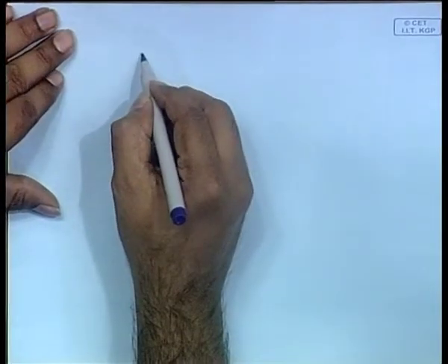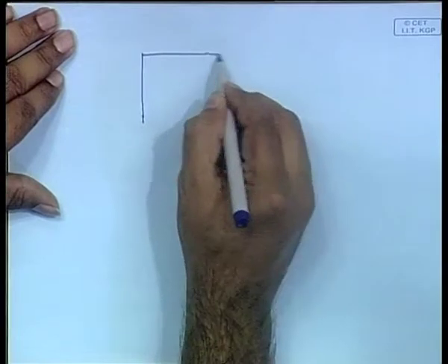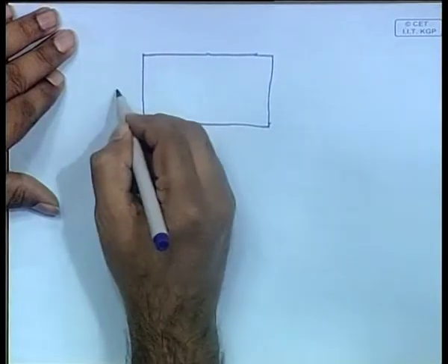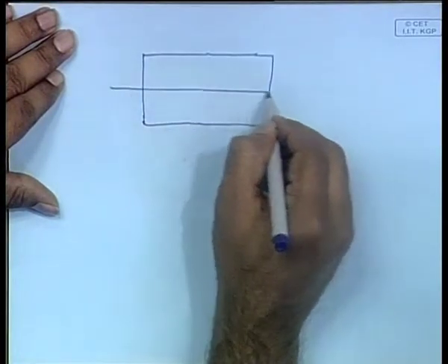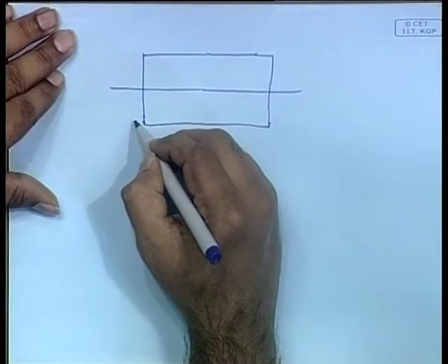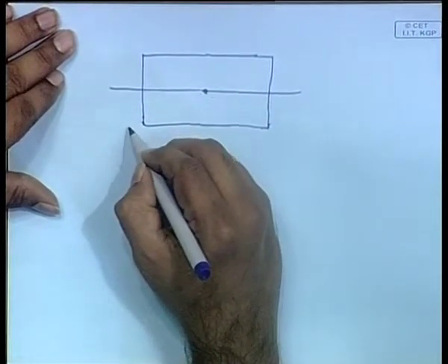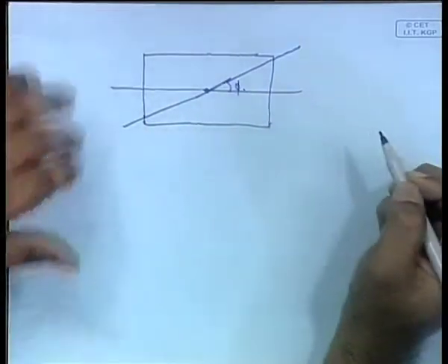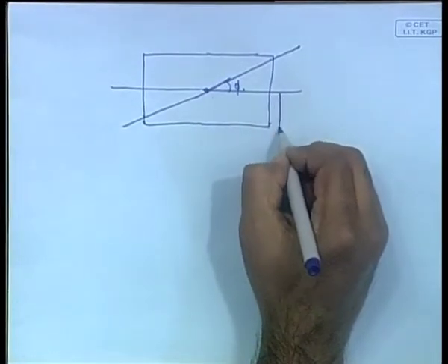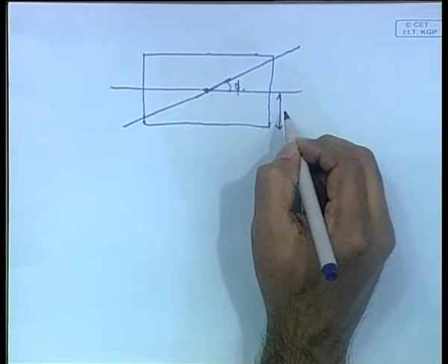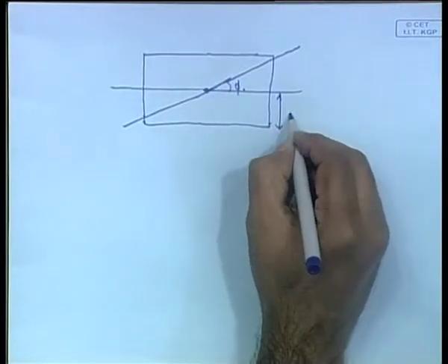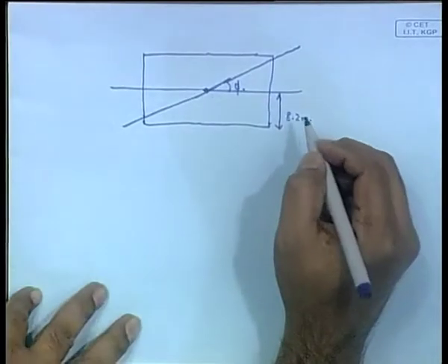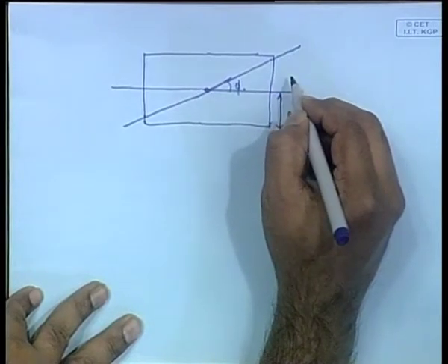Okay, now it is a box shaped vessel. You are told that the draft is given. We want this phi. Now, you are told that this draft is final, so this is 8.2 meters. Then you are told that the depth of the ship is 12 meters. Therefore, this is 12 minus 8.2, 3.8.